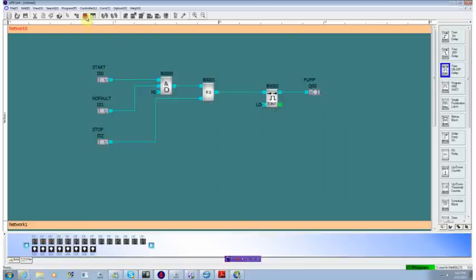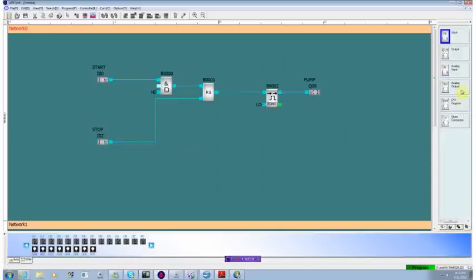And the last thing we want to do is change this fault handling. We said that this was a pump. We're going to assume that it's actually a submersible pump and that this is a CO detect input. Well, currently it's a digital input that's coming in. We're going to delete that one. And we're going to go back to our I/O types and see that we have an analog input. Well, CO detect is typically a resistance to ground, and it will drop below a certain threshold when we have a leak in the seal. We want that to be our condition that turns off, disables the pump.